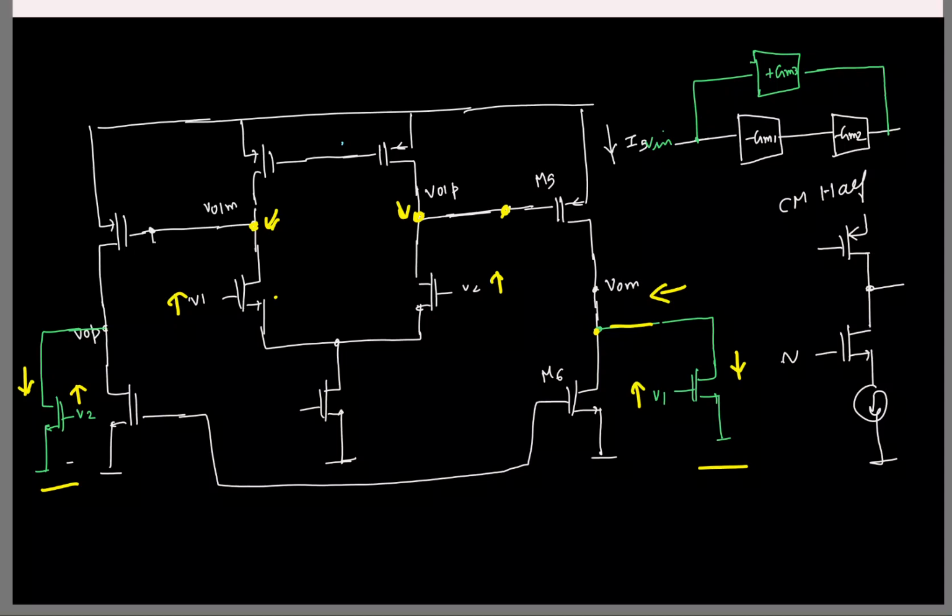We have a common mode disturbance and looks like the output is responding to the common mode change. So is it good or bad? Bad, right? So CMRR will be poor. So looks like although differentially this is doing the compensation, it is killing us in the common mode case. So instead of connecting two GMs like this, what can you do?